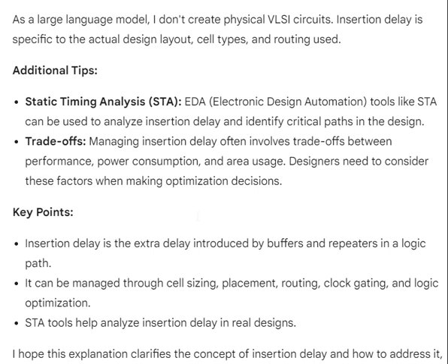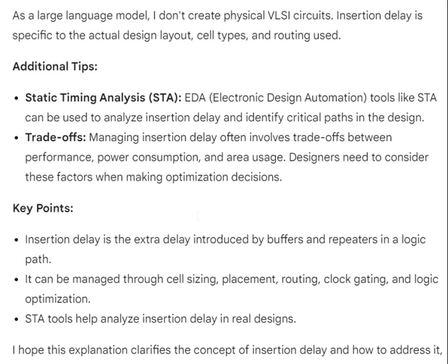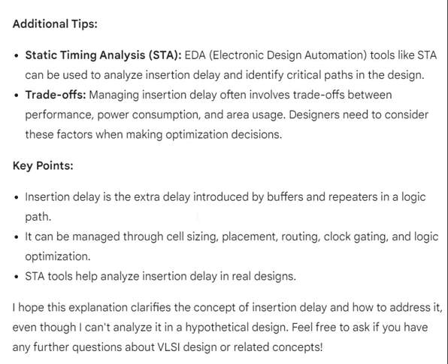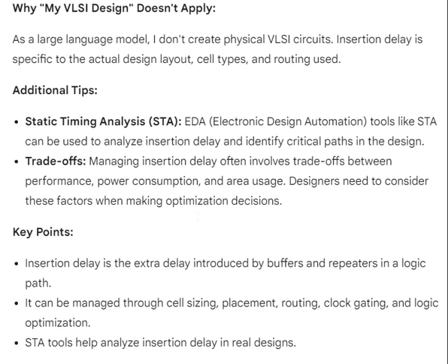Trade-offs: managing insertion delay often involves trade-offs between performance, power consumption, and area usage. Designers need to consider these factors when making optimization decisions. Key points: insertion delay is the extra delay introduced by buffers and repeaters in a logic path. It can be managed through cell sizing, placement, routing, clock gating, and logic optimization. STA tools help analyze insertion